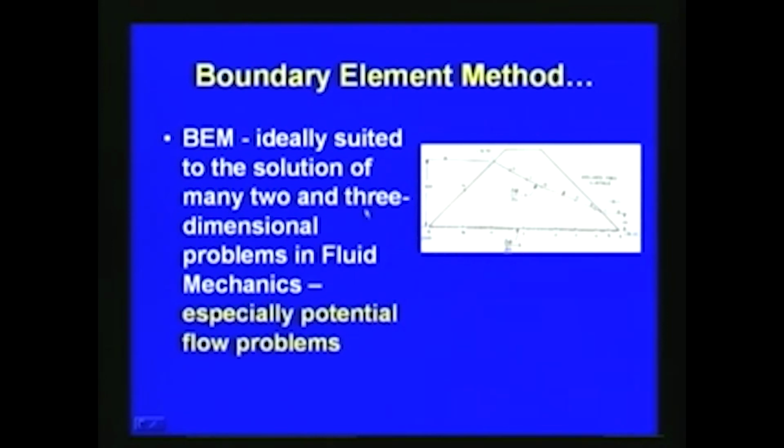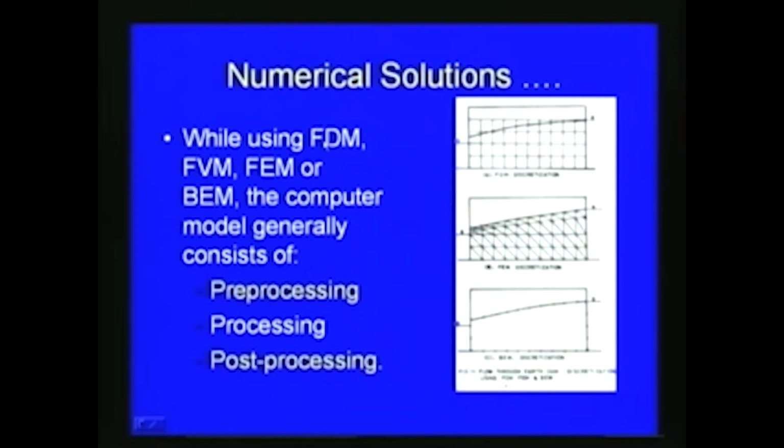To solve the full Navier-Stokes equation, this methodology has some limitations, but advanced techniques like the dual reciprocity method can be used. Otherwise, the BEM methodology is much more used to solve potential flow problems. So, in comparison, while using the finite difference method, finite volume, finite element method or boundary element method, we